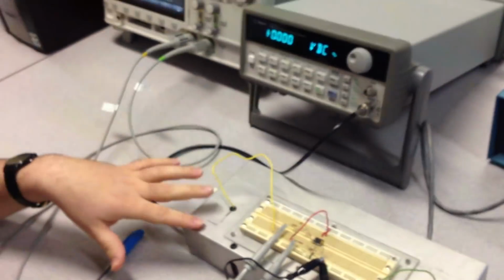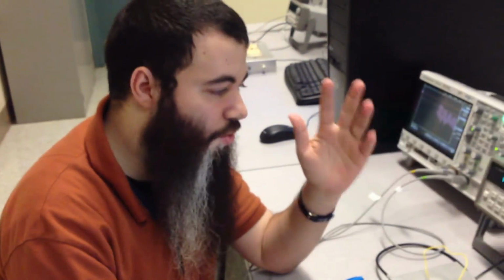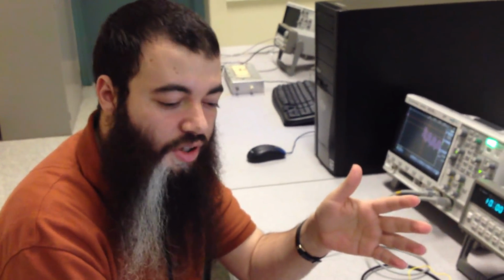What we are required to do in this experiment is to input a square wave of some duty cycle. We'll choose 20% duty cycle, and see the spectrum in the output compared to the input. In the lectures, you learned that if you have a signal, you could take a Fourier transform, or a Fourier series if it's periodic, and get the frequency response.